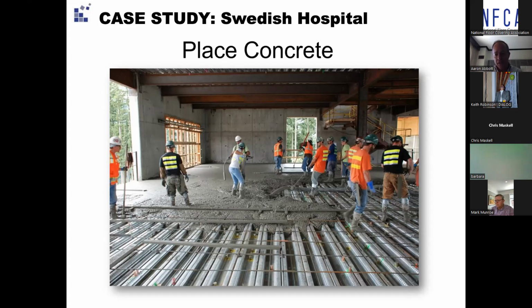In this particular case, I think it was when it reached 75% of its design compressive strength, which was maybe 5 to 7 days. This was very early, at least in one phase. But the experts need to weigh in: the structural engineers, the architects. We've got to get everybody to talk.